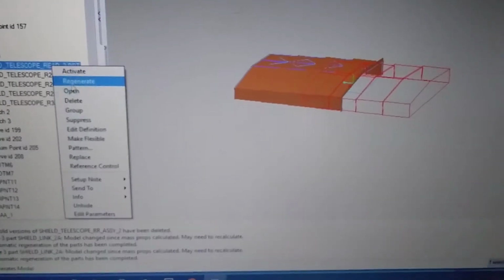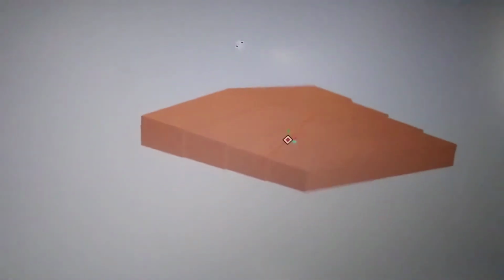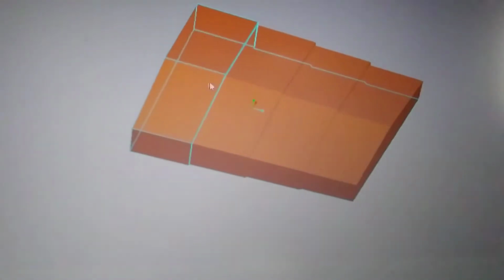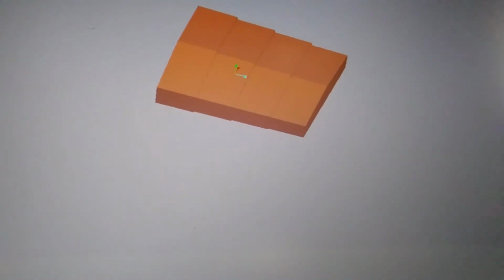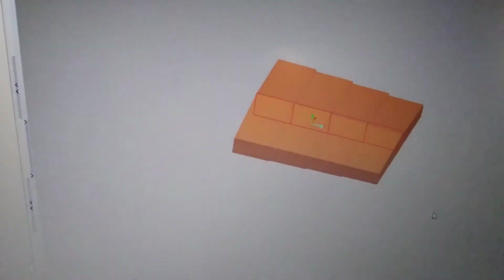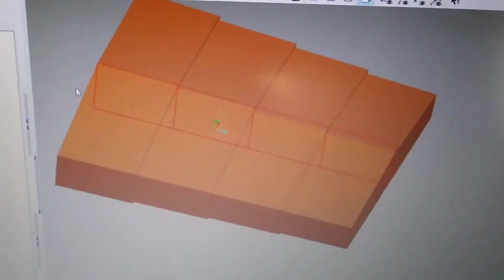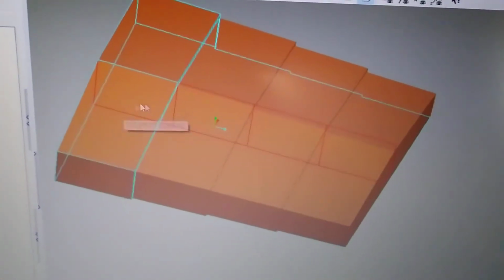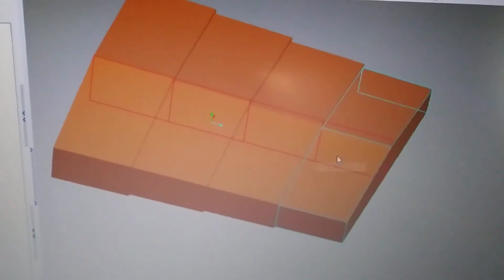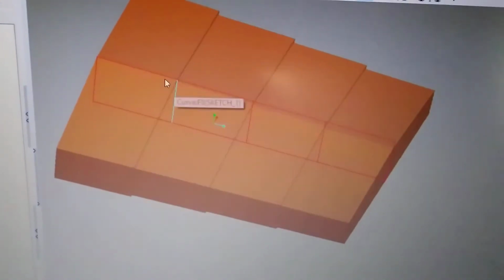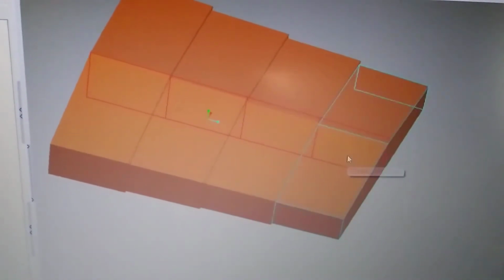Firstly, I have the original solid model. This cannot be called a skeleton, just a simple solid model. And there is a sketch here. It tells the total length and the height. Most important is it was divided. This curve is divided equally into 4 sections.